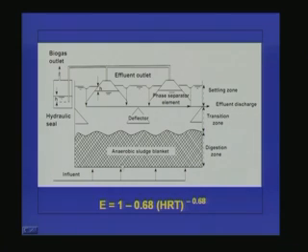This anaerobic sludge blanket is nothing but active microorganisms. These active microorganisms will be coming in contact with the organic matter present in the wastewater. As a result, biodegradation will be taking place and new cells will be generated, and as a byproduct carbon dioxide and methane gas will be produced. Everything will be moving together. That means gas, liquid as well as solids will be moving in the upward direction like this. This is the digestion zone of the reactor, and afterwards what we can see here, a transition zone is there.